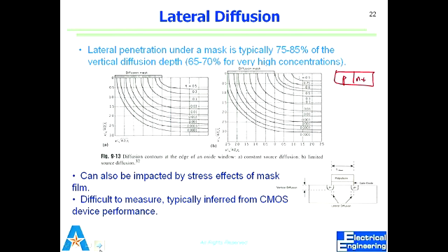Now, when they are overlapped, it doesn't matter whatever voltage I apply because they're already shorted. A very crude form of what I'm drawing here is what are called short channel effects. So there's much more to it. We have to maintain a certain amount of length for my gate. So what we actually end up doing is we don't make them like this.